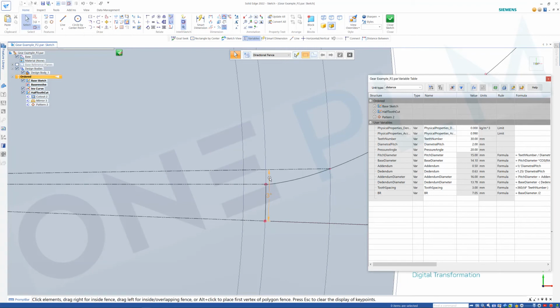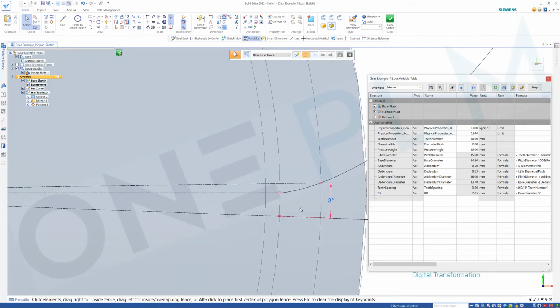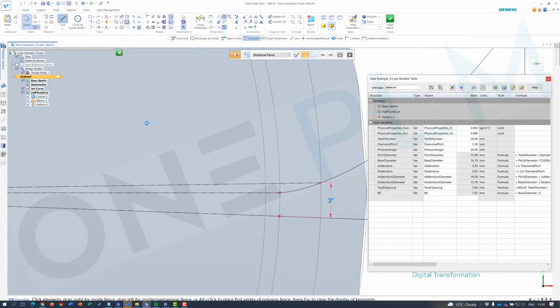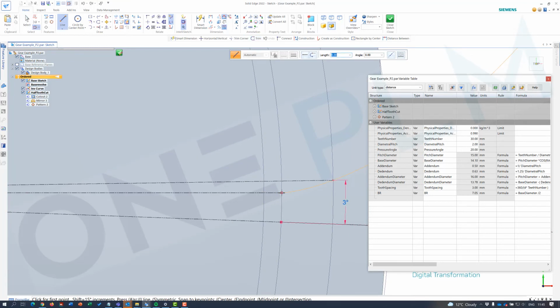So you can see I'm just going to move this angle dimension out of the way, just so that's not in the way. So this line that we've got on there should have been, so for this we actually should have created an additional little line that goes to there. So you can hover over those two lines. It should then allow us to go and pick up the intersection point on there, or we can use our I key to pick up that intersection point.